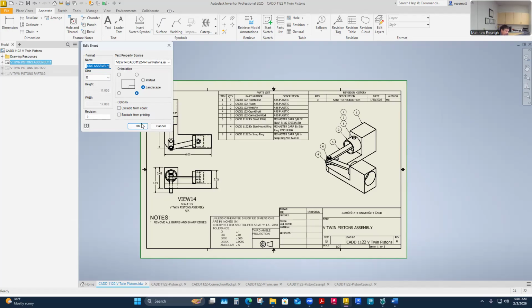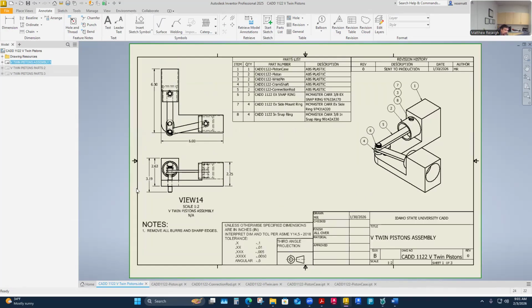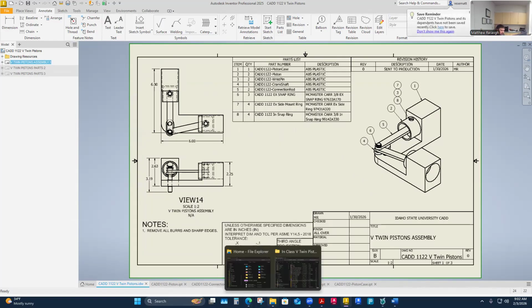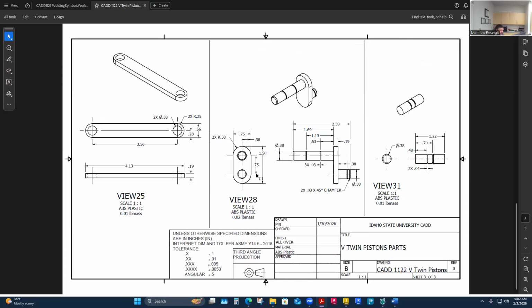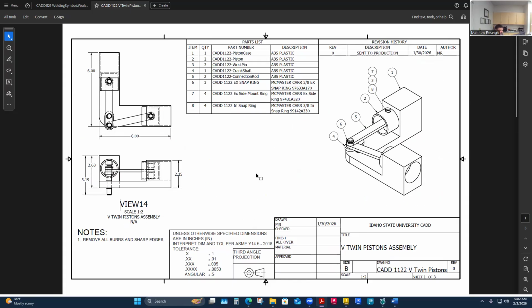It can also be really annoying if you're working with somebody else's prints and one page is not printing. Sometimes you need to go in there, and maybe something has accidentally been toggled off not to print. So when getting your PDFs with the right sheets in the right order, pay attention to that. My biggest word of advice is to always open up your print after you've saved it as a PDF and preview it. Don't send somebody that until you preview it, because a lot of times you don't catch your mistakes until you look at them here.